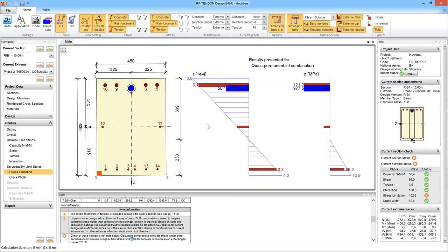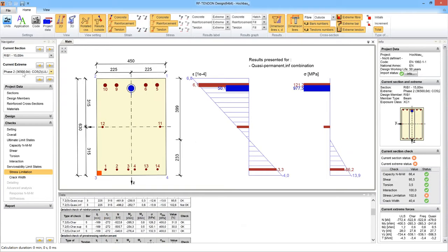it happens during the pre-stressing in the fibers where you have the pre-stressed tendons. Then, due to the fact that you measure all the forces in the tendon, you can afford to decrease the r sup and r inf factors. But in this case, you can see that it is phased at 100 years. And in this case, either we say, okay, 2% is not that big a problem, or we would have to increase the depth of the cross-section, or we can also increase the concrete grade.